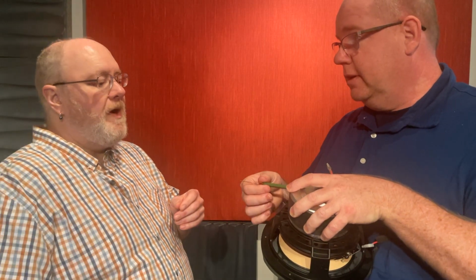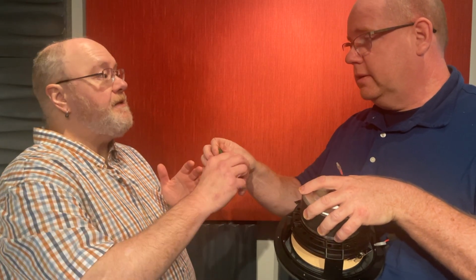So if I have, let's say my tweeter, let's pretend this is a tweeter. It's like 16 ohms. And I want to drop that. I stick a resistor. Well, it does change the impedance that the amplifier sees, but it's more about SPL drop. That's what you're focusing on. SPL drop. Sound pressure level? Yes. Okay.